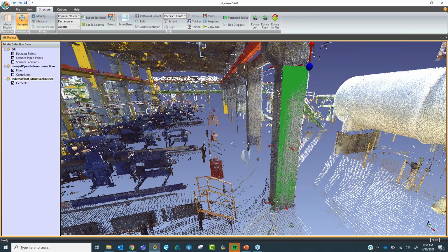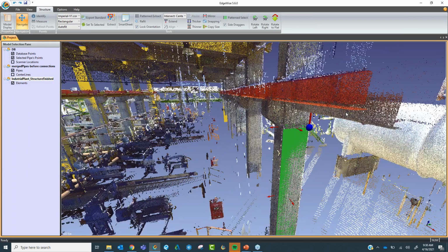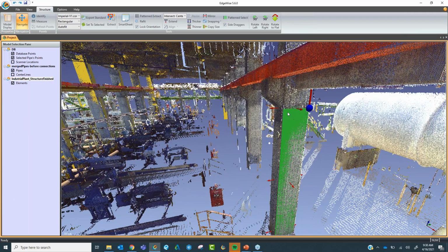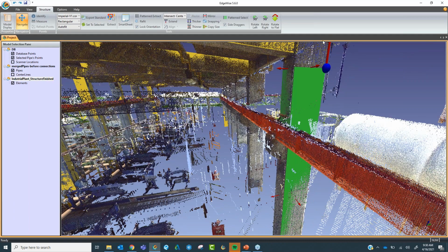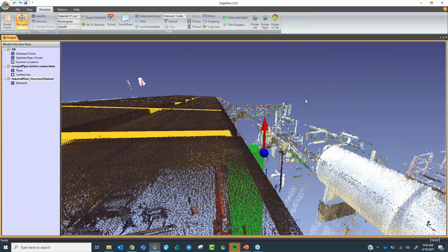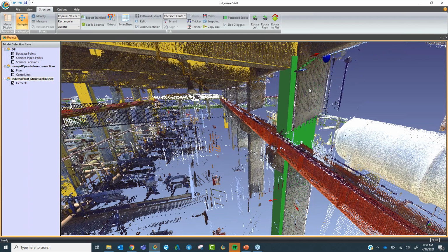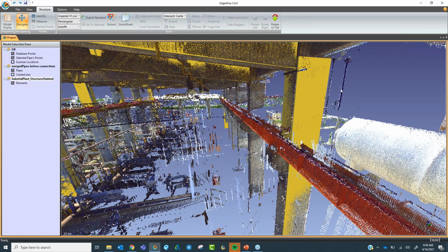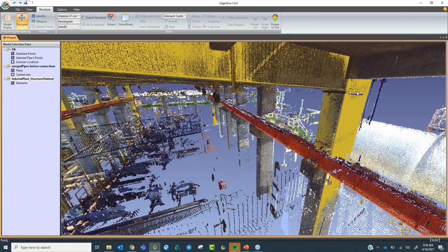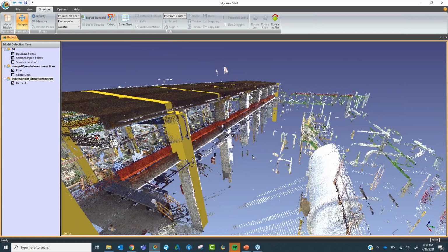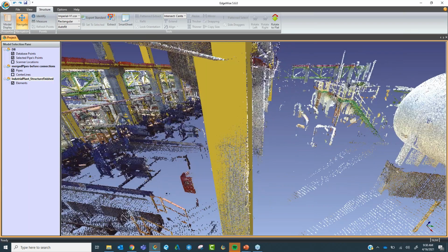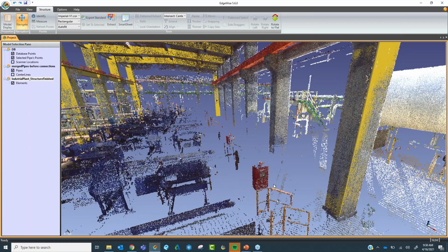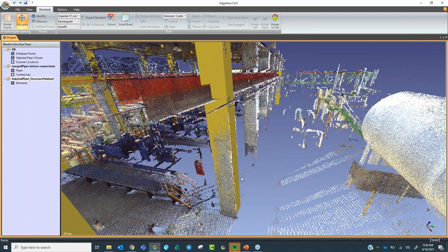Now I noticed that this one has a corbel on it here. So I would probably try to follow that around at least, and then take the rest of this portion up. But in this sense here, I can go ahead and take it up right to the roof, okay? Oh, let me hit escape there. Grabbed a hold of it and moved it. So there it's going ahead and it filled in the point cloud. It auto fit to what it found was the extents of the point cloud data, like the density itself.